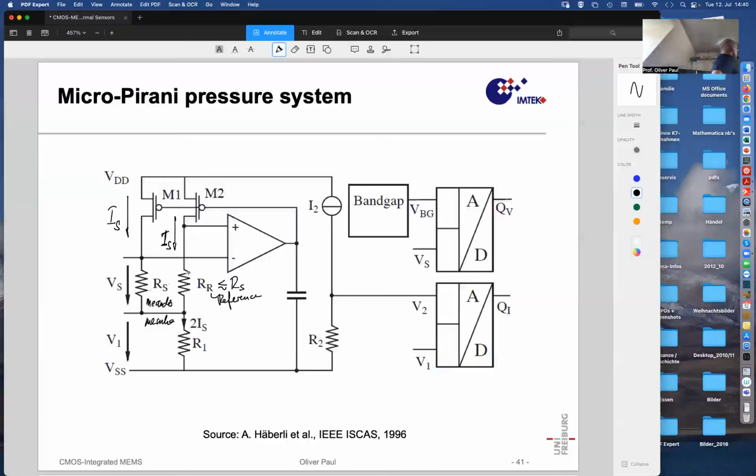and then the same currents go through these two resistors, and they produce a voltage, which let's say here is certainly smaller than the voltage here. No, sorry. I wrote it the wrong way around. RR is slightly larger than RS. So the voltage drop over RR is larger than the voltage drop over RS because RS is smaller. However, RS is also heated.